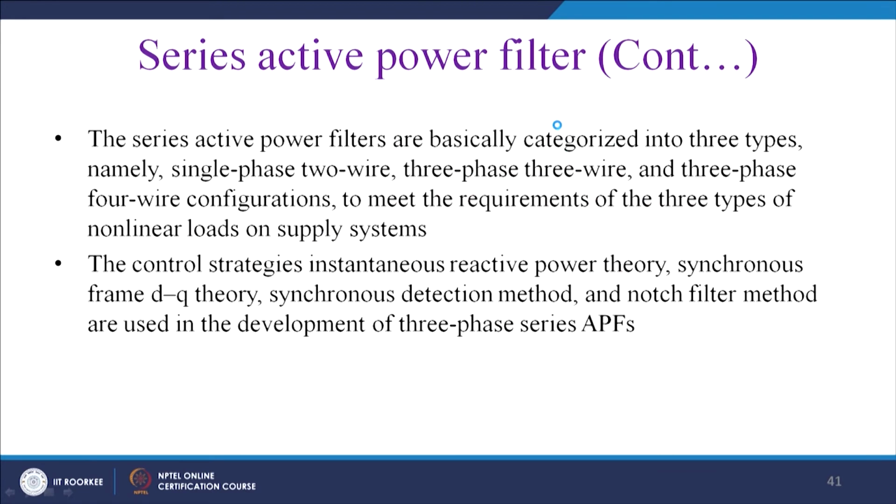The series active filters are basically categorized into 3 types: single phase 2-wire, 3 phase 3-wire, and 3 phase 4-wire, to meet the requirements of the different kinds of power supply available to us. The control strategies of instantaneous reactive power theory, synchronous frame DQ theory, synchronous detection methods, and notch filter methods are used in the development of this active power filter.